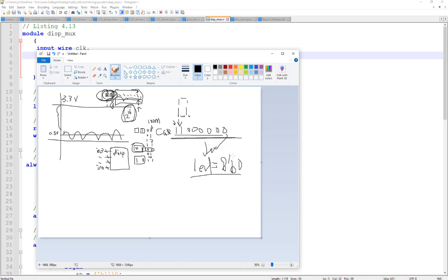It's just a byte, right? Since you have done the LCD lab and the byte is available, you should be able to find a way to send the byte to the LCD display. Just connect to the GPIOs. The FPGA module, the Verilog module, has an interface with the vector, right?